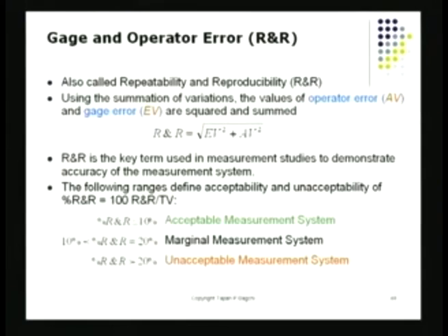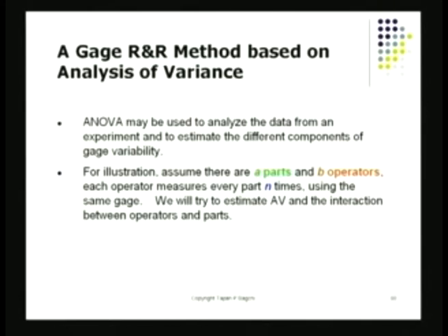In certain cases, the measurement system itself can be totally unacceptable, like when the gauge readings turn out to be such that they are contributing almost 20% of the error. That's in the final variation you are contributing to the measurement system. That's not such a good picture. You have to make sure your parts, which is what you are really after, are measured correctly.